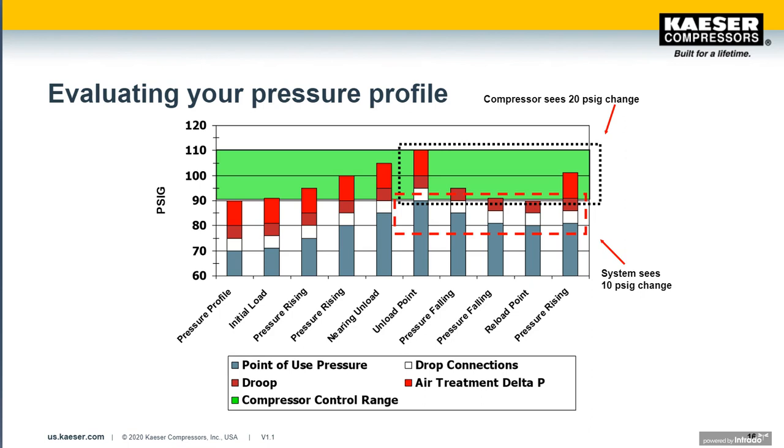But while we've reduced the operating pressure, which is reducing energy, we're also having a longer unload time, which allows the separator to blow down and the compressor to reach its true unloaded power. So all good things. On the negative side, we've increased the customer's system pressure and increased that artificial demand. So the next step would be to drop the pressure in the compressor room, either via dropping the load and unload set points again, or perhaps adding a flow controller to reduce the system pressure back to the lowest acceptable level down there at the point of use.